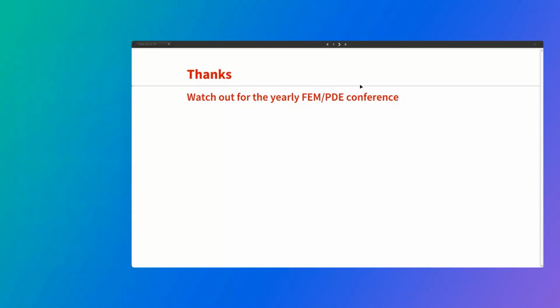Okay, so for modeling the factor of safety for soil slopes, the normal approach is to perform shear strength reduction analysis. In essence, reduce the soil shear strength parameters, typically cohesion and angle of friction, until failure occurs. Yes, we have a shear reduction example in the application. In the slope application, you will find that shear reduction analysis.